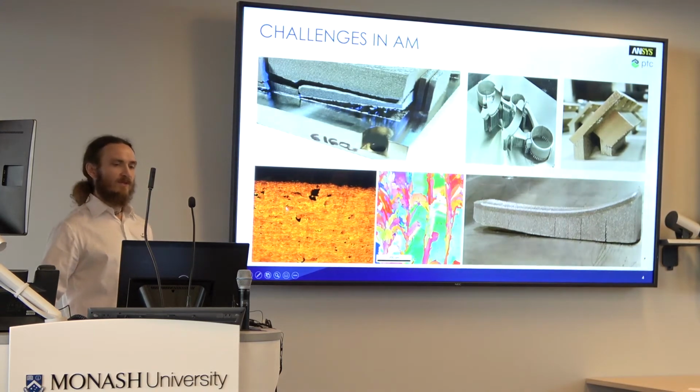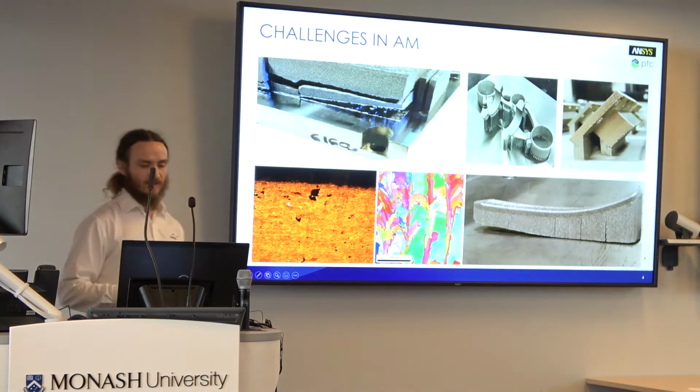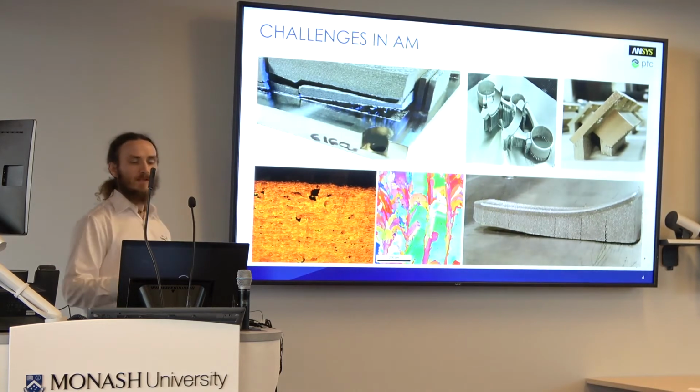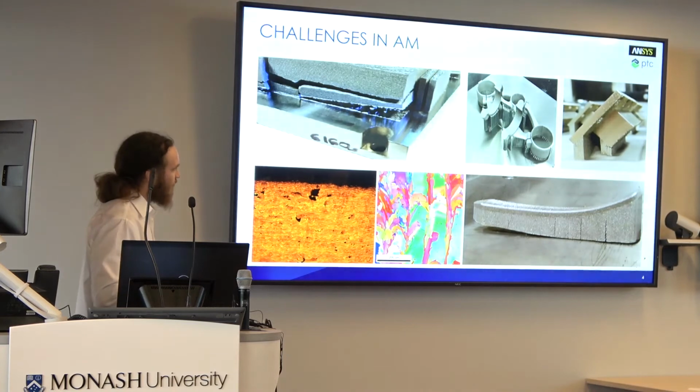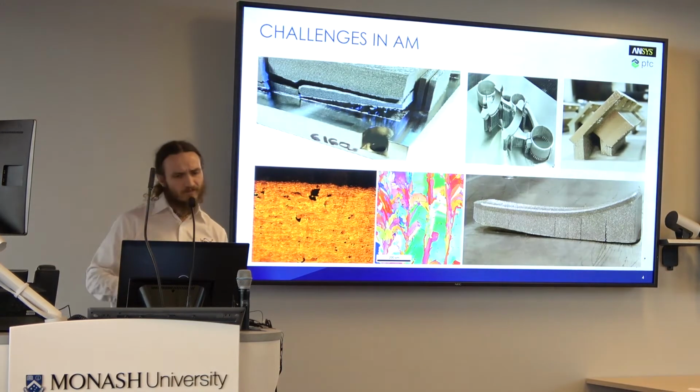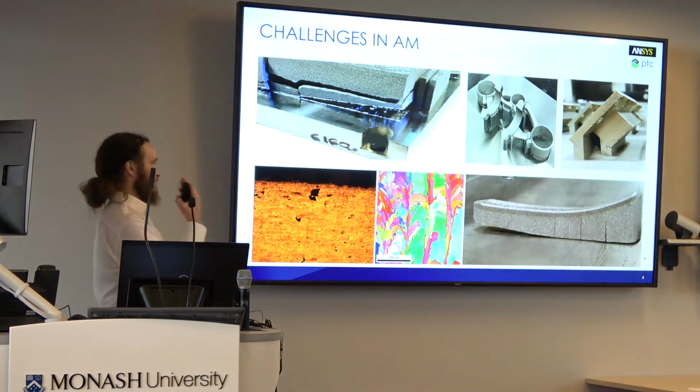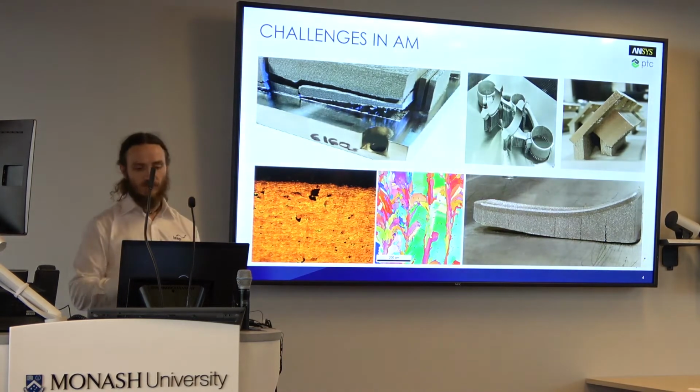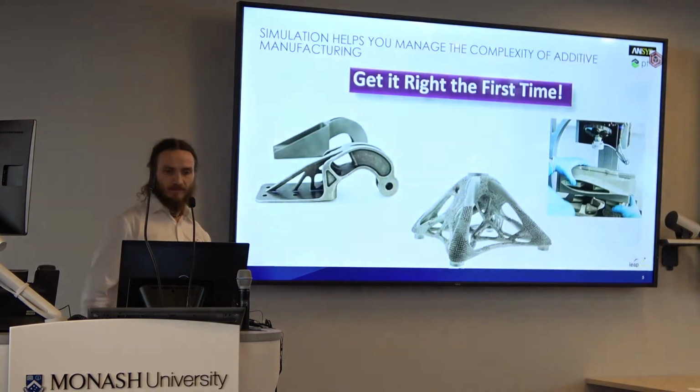And then there's also the question of the metallurgy of the part, because essentially we're taking powder and melting it with a laser, and that's developing the local metallurgy, which will affect the material properties. So our whole process affects the resulting strength and durability of the material and the part.